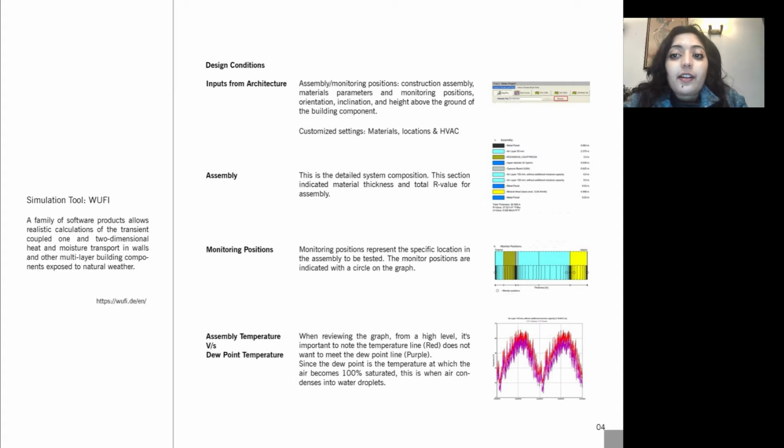You can specify the heat transfer coatings, radiation absorption, the emission, etc. You can also specify the heat transfer and the possible coatings that you want to apply to the facade. So basically these are the default settings of the material. These are already preloaded into the software and you can customize this if you have material information from the catalog.